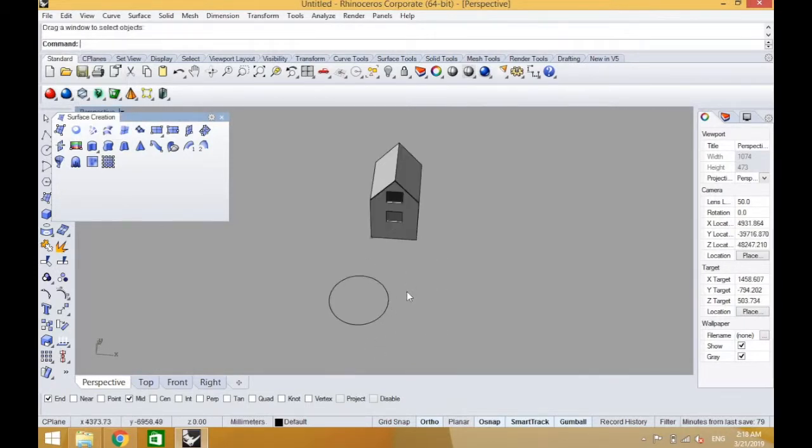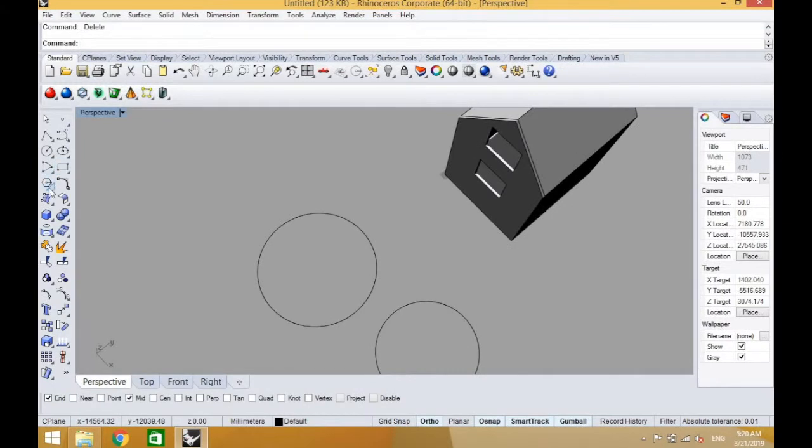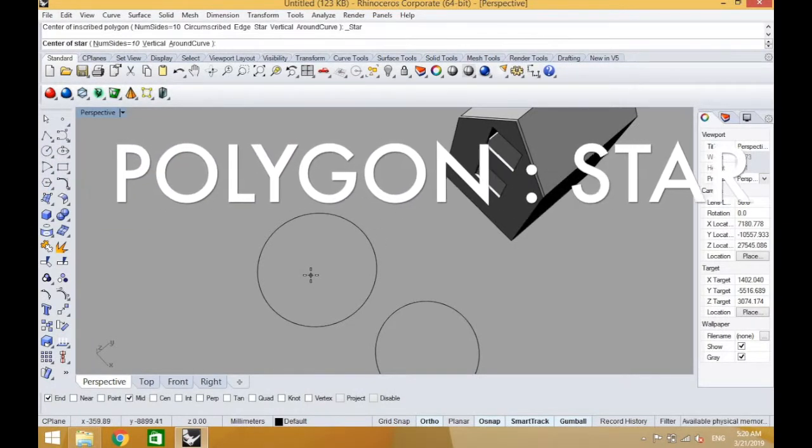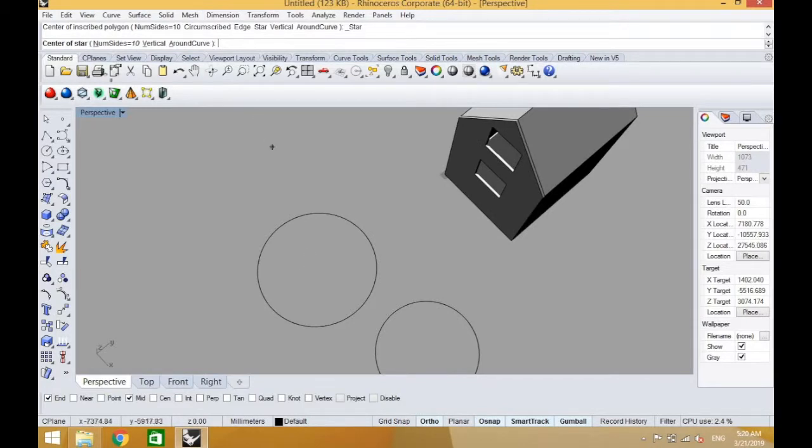Let's get started. So yeah, you have this thing such as the polygons in Rhino itself. All we need to input is the number of sides we require. So we input, say I put 16, and second to this, after inputting the number, we can adjust the angles required. Let's go closer to a 90 degree angle.